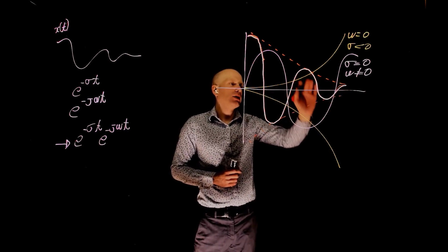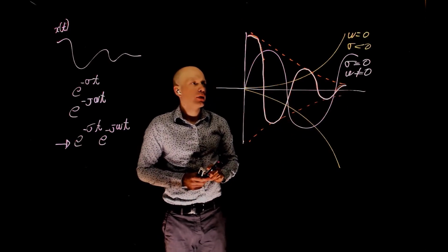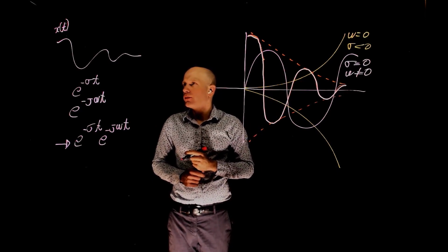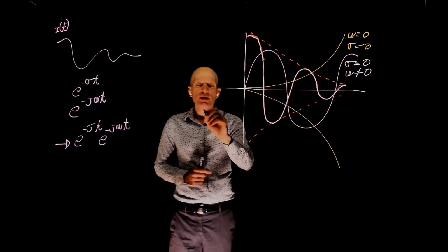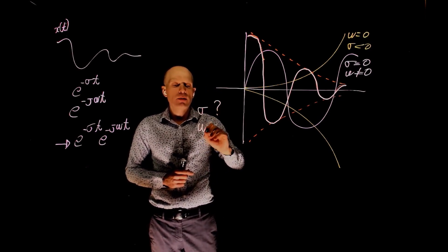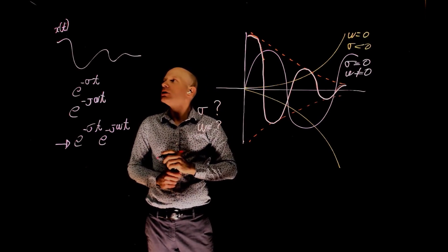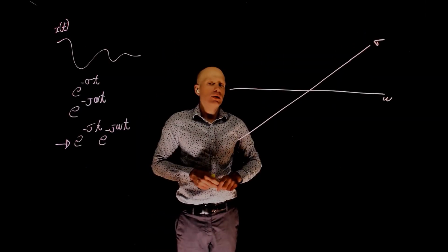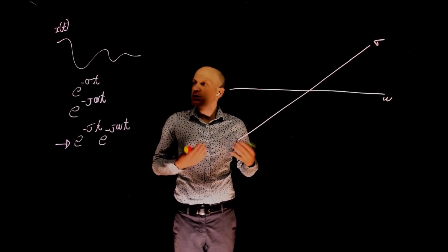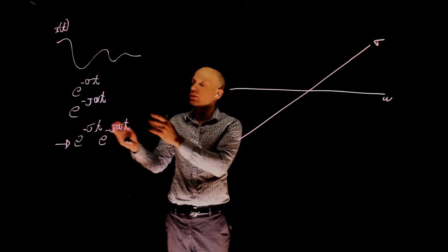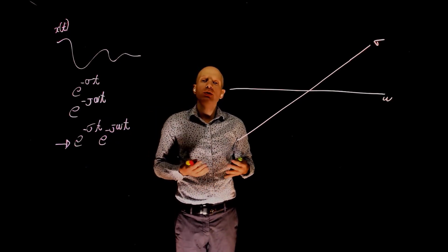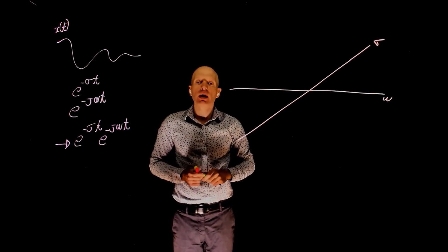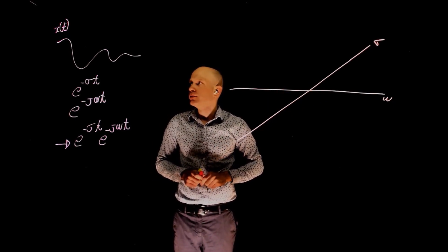There is a sinusoidal that decays over time. In this case, sigma and omega are both different than 0. The question is, what sigma and what omega do we need to create x of t? To do that, we need to create some signals and compare those signals with x of t. Let's call those signals that we create by using random combinations of sigma and omega a probing signal.